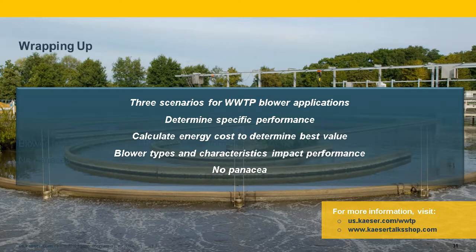And then where you offset the ports on this twisted lobe, you're able to increase the blower speed, but there's still no internal compression. But the increase in speed does increase the performance, and that is very similar to what the screw blower does. But the screw blower has a defined internal compression, whereas the twisted lobes do not.